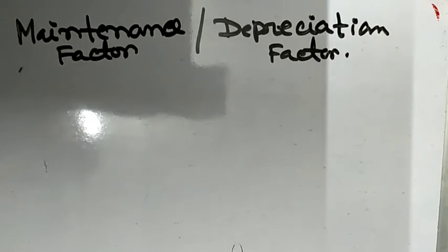Unless there is a regular lamp and lamp fitting cleaning schedule, there is bound to be depreciation in the light output due to deposition of dust and soot as a dark film on the light source. Deposition of dust and soot on the lamp is technically called soiling of the lamp, and depreciation of light, in addition to the soiling of the lamp, may be due to the soiling of lamp fittings and other reflecting surfaces such as ceiling and walls.